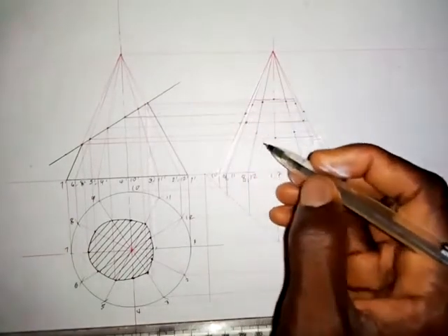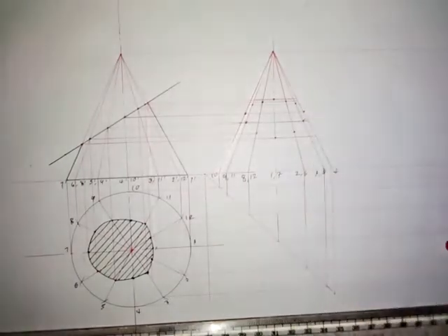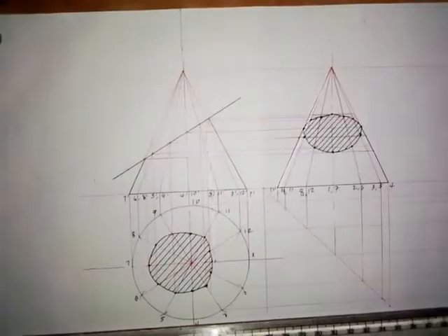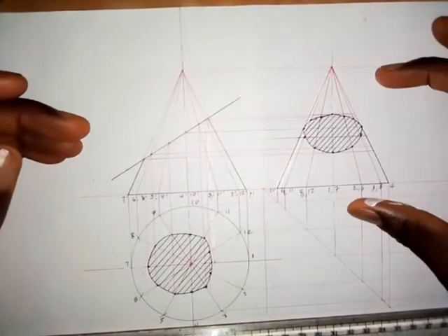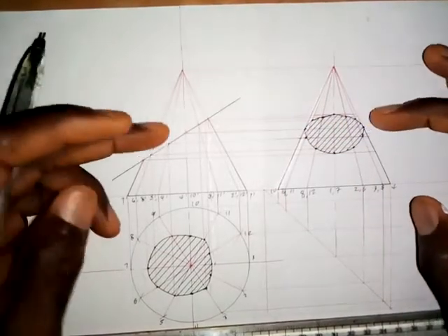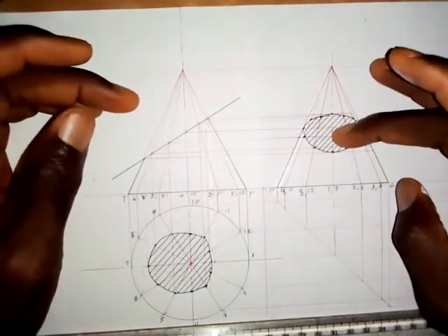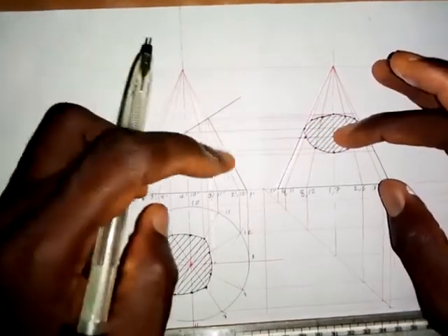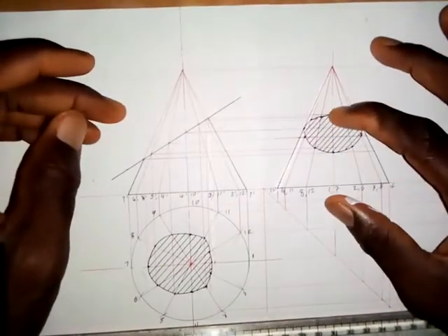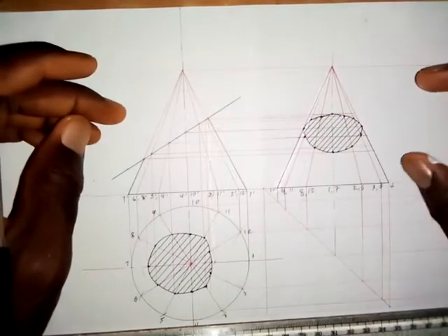So we are going to join these points together with the use of a French curve. I'm going to do that, and then I'll come back and show you what I've done. All right, so this is what we are going to have as the end elevation. This surface is rough. When we cut it here and we remove this part, we are going to see this part looking rough. As I said, if this happens to be a solid object, this is what we are going to see. So this is the end elevation in direction of ROP as said.